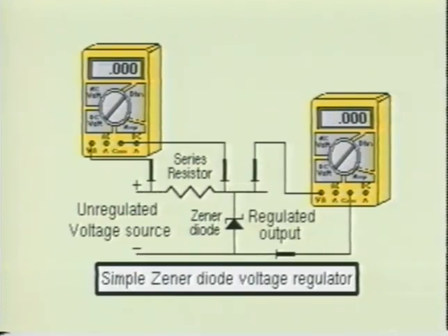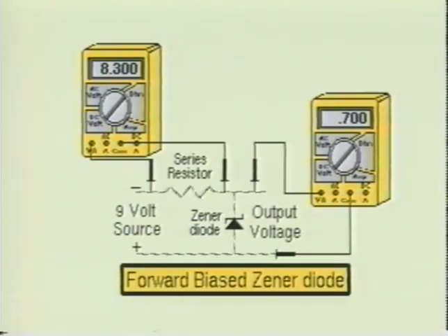When the reverse bias is reduced below the avalanche voltage, the current will return to its off-state condition. When the Zener is forward biased, it acts as an ordinary diode. Therefore, the Zener is usually operated in its reverse bias mode.